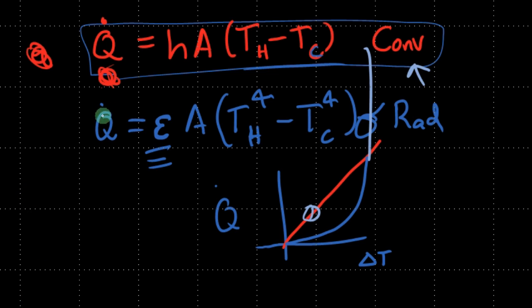So again, there are two types of heat loss which can occur: convection and radiation. Convection can either be forced, or natural convection, which is just something sitting in the air and it loses heat due to the rising and falling of air, which is hotter and colder. Differences in densities result in some type of spinning air motion. You can find some ideas about it online. You sort of see it with your tea or your coffee, how the water vapor swirls around, and that actually induces a sort of flow of air, which is why it's called natural convection. There's also conduction through air, but that's not really important.